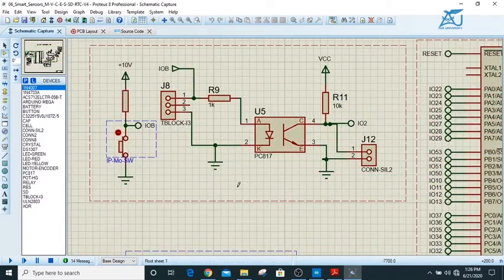Now starting from this circuit, here we use an optocoupler. The optocoupler protects the circuit from high voltage or high current. When the switch is closed, the infrared LED puts the emitter of the optocoupler in active mode and the DC voltage can be drawn from here. No matter how much voltage we put here, the VCC will always be constant, with the small variations we can make in the circuit.